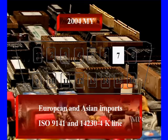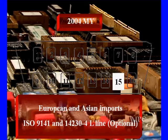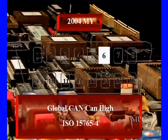Back to that pin 7 again, we find ISO 9141 and KWP 2000, which is the 14230-4 K line. That's used there on most European and Asian cars. Fairly universal. Pin 15 is not universal. You'll find times you've got battery voltage on here. And where it is used, it's used with 9141 and 14230, which is on the Asian and European imports. Pin 6 is new. Good news. Finally, global CAN high.